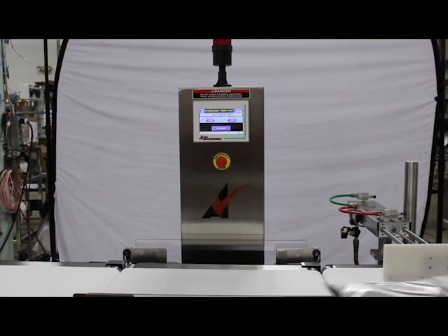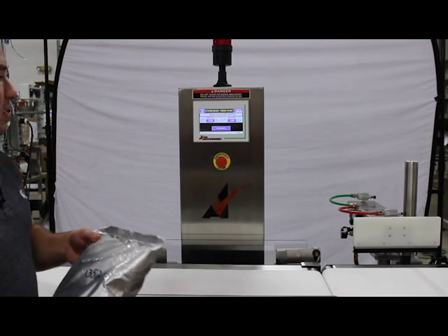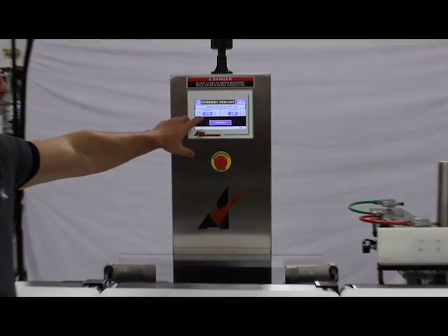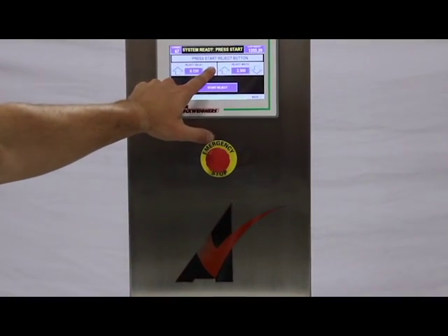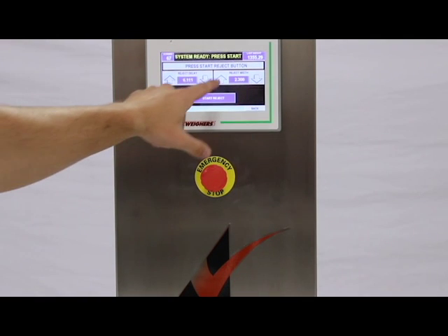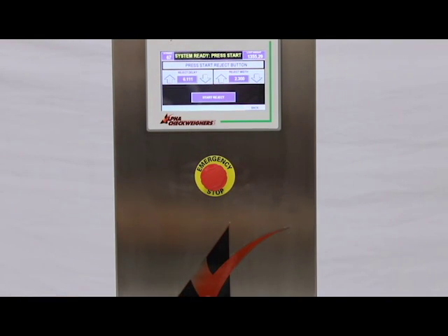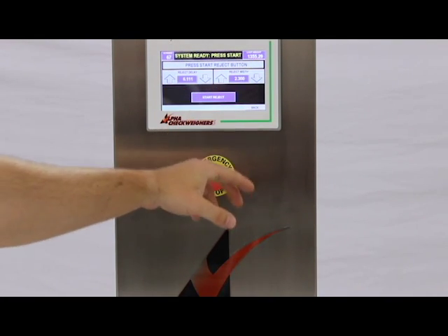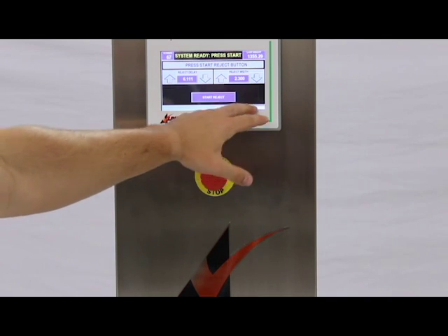Okay, so that was actually timed pretty spot on. Like I said, if you needed to fire off a little bit faster, all you would do is lower this and you can see the seconds go up and down. Same with the width. If you needed it to extend a little bit longer, you can mess with the reject width, but that's how you set up your reject.